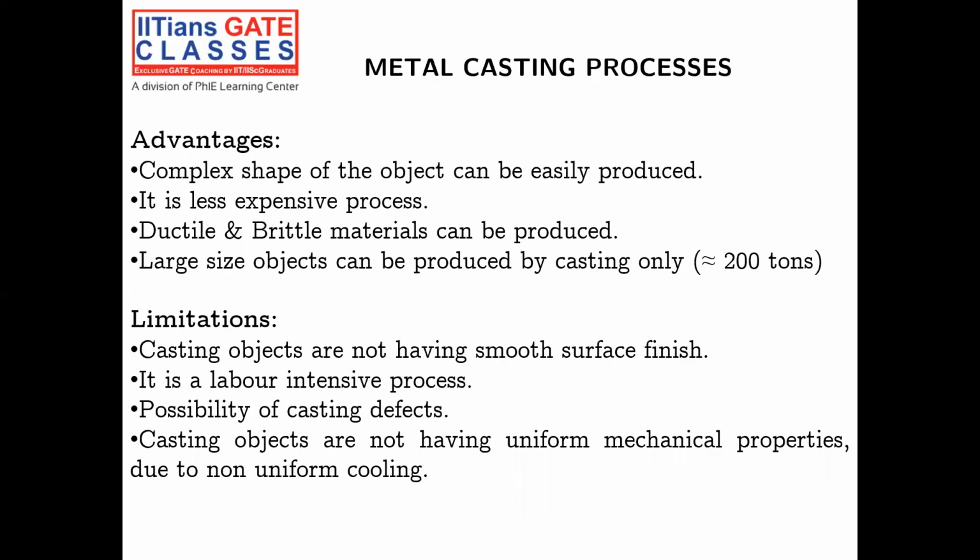Okay, next. So what are the advantages of casting? So you can make very complicated shapes by using the casting. Let's say you have some engine block. So the engine block of any machine or any automobile has very complicated parts in it. The outer part of the engine block can be completely manufactured in one go by using this metal casting. So highly complicated shapes can be manufactured by using metal casting, and the procedure is very less expensive. Very less expensive means you can use the mold cavity again and again, that is your permanent molds, to make mass production. So it is very less expensive.